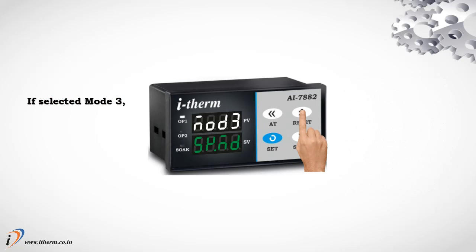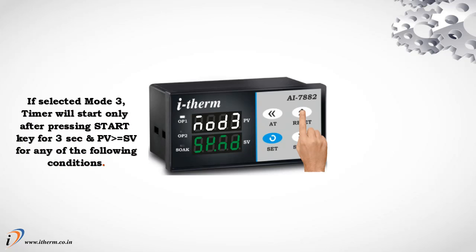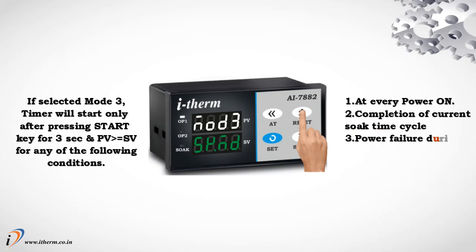If selected mode 3, timer will start only after pressing start key for 3 seconds and process value is greater than and equal to set point value for any of the following conditions. 1. At every power on. 2. Completion of current soak time cycle. 3. Power failure during soak time is in progress.